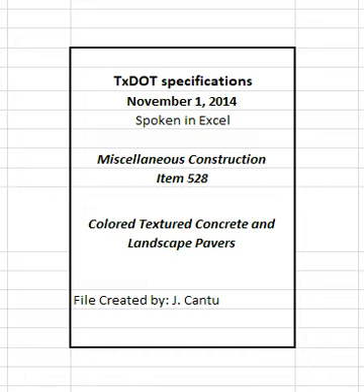Do not compact within 3 feet of the laying face. Continue compaction until lipping has been eliminated between the adjoining units. Compact all work to within 3 feet of the laying face at the completion of each workday. Spread joint filling sand as soon as practical after compaction, but in all cases before the termination of each workday, before acceptance of the day's work, and before permitting construction traffic. Allow joint filling sand to dry, and then sweep to fill the joints. Compact the pavers and joint filling sand with a single pass of the compactor.